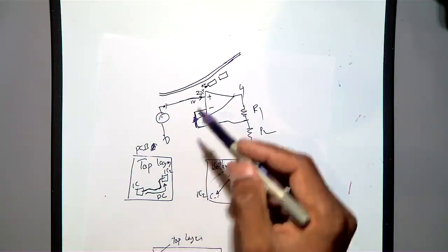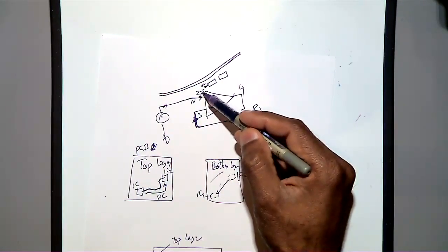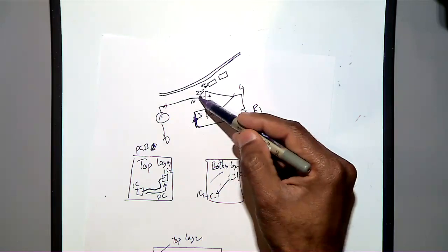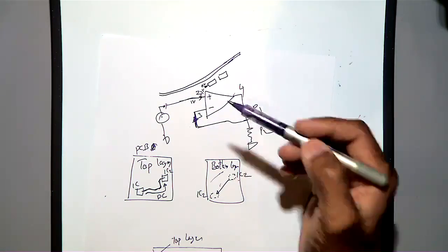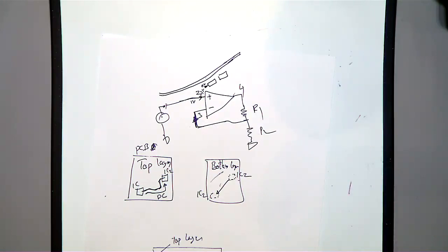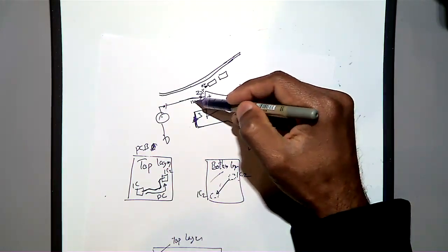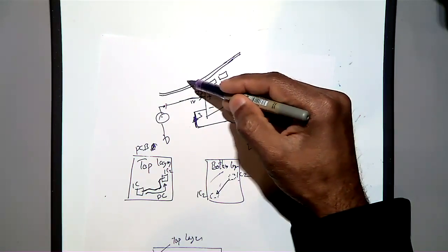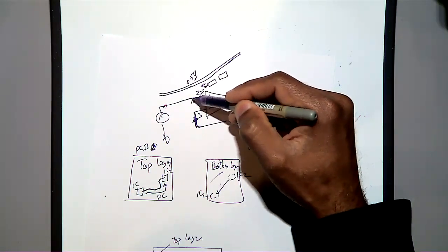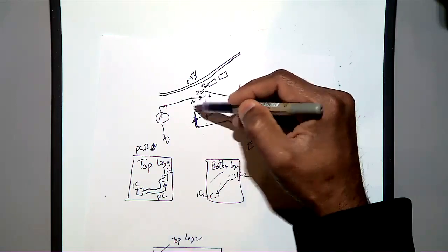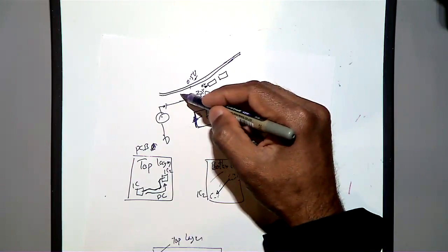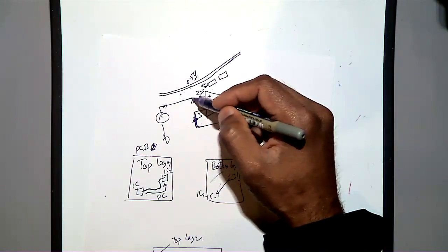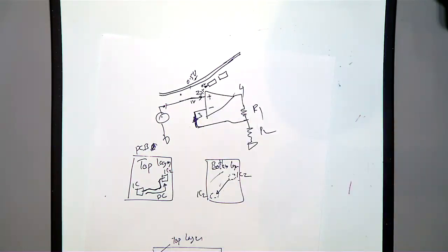And when it is a capacitor, the capacitor will block DC, but because this is high frequency, there could be some leakage through this capacitance, because a capacitor will permit AC to pass through. The same will happen with even a track. If this is 1 volt, and this close by may be 0.5 volt, then there is a potential difference between these two. So that also can form a capacitor, and create some leakage.